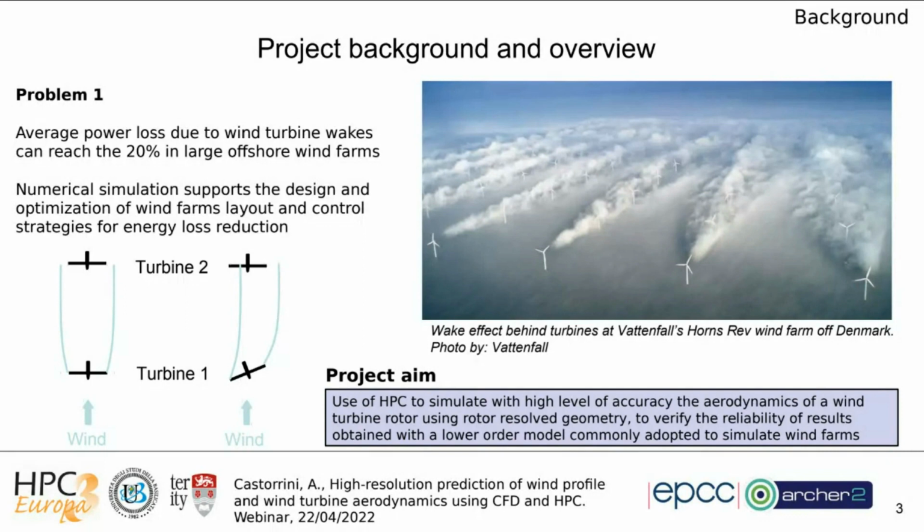So one solution that the technology is trying to adopt is to control and deflect the wakes a bit by orienting the front turbines with a so-called yaw angle, misaligning the rotor, and in this way using the effect of the thrust of the rotor to deflect the wake and free, hopefully, a little part of the rotor behind and save some energy.